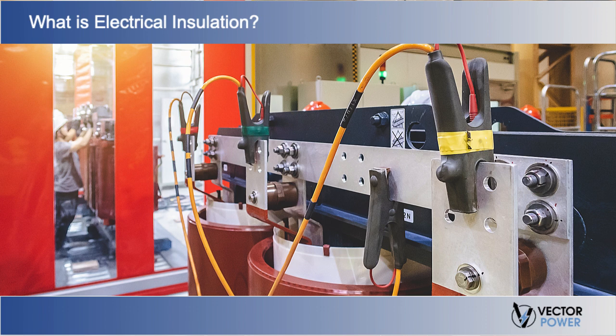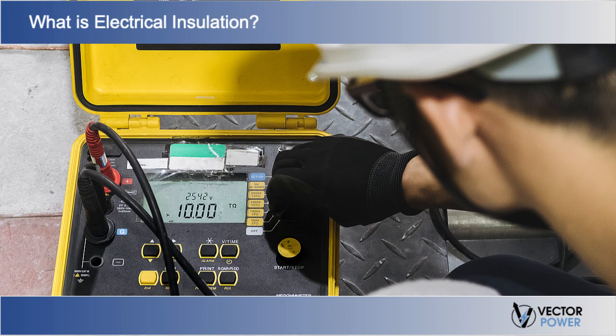It deteriorates with the ingress of water and with elevated temperatures. For high voltage applications, dielectric strength is the most important single property of the insulation. Insulation resistance measures how much current is drained away from the conductor through the bulk or along the surfaces of the dielectric.